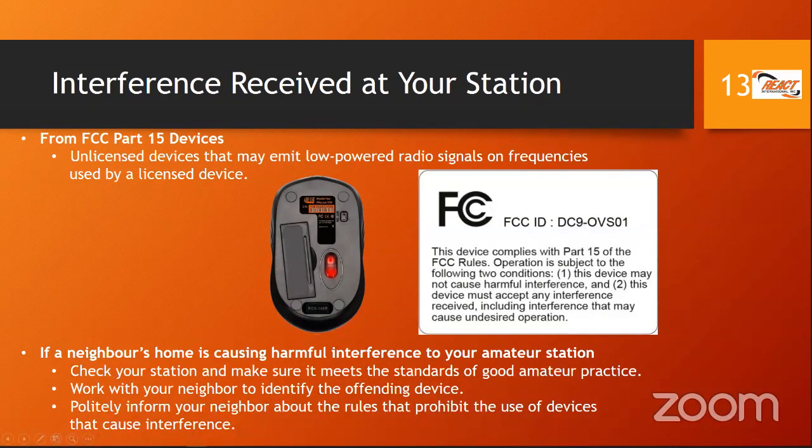So the point that is made here is if a neighbor's home is causing harmful interference to your amateur station, one, check your station to make sure it meets the standards of good amateur practice. Make sure all your connectors are tight. Make sure you use good quality cable. If you're using poor quality cable, you might be inviting interference into your own station. So, check yourself first. That's what the first point is, before you go and look for your neighbor to see what they might be causing you.